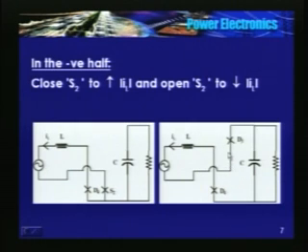So there is a diode in the upper half, D3, load, D4 back to source. Source, D3, load, D4 back to source. Same thing, same principle. IL decreases provided the value of Vm is less than V0, or Vi is less than V0. When I open the switch, current decreases. The principle of the operation is the same. Okay.